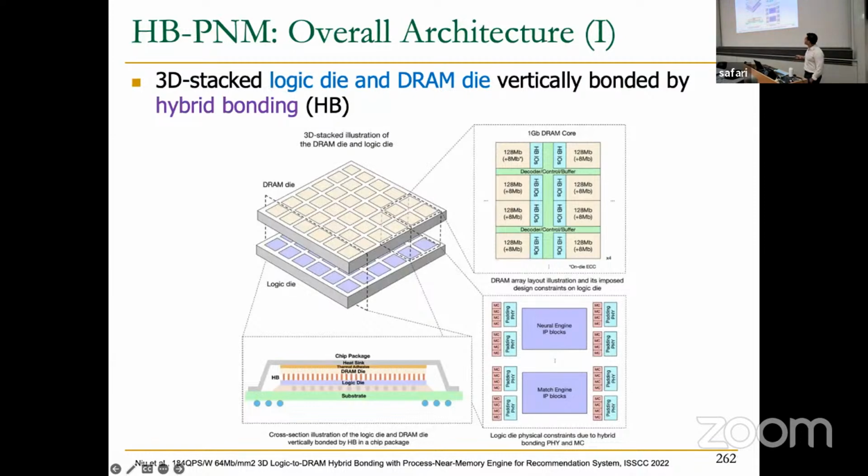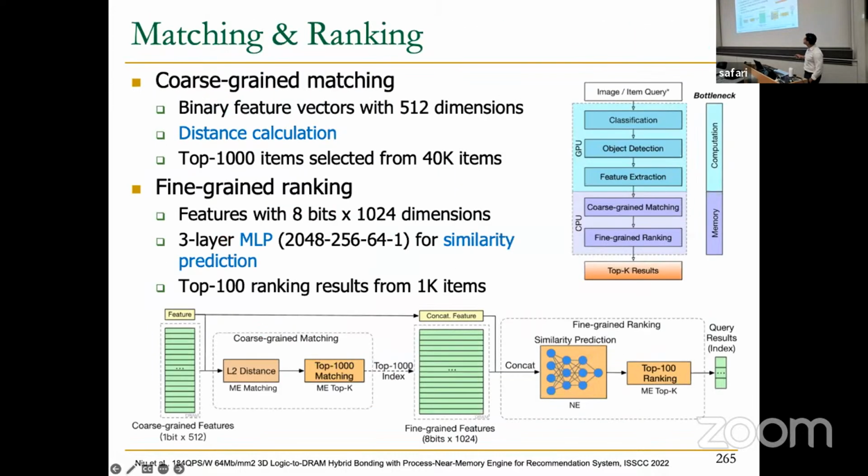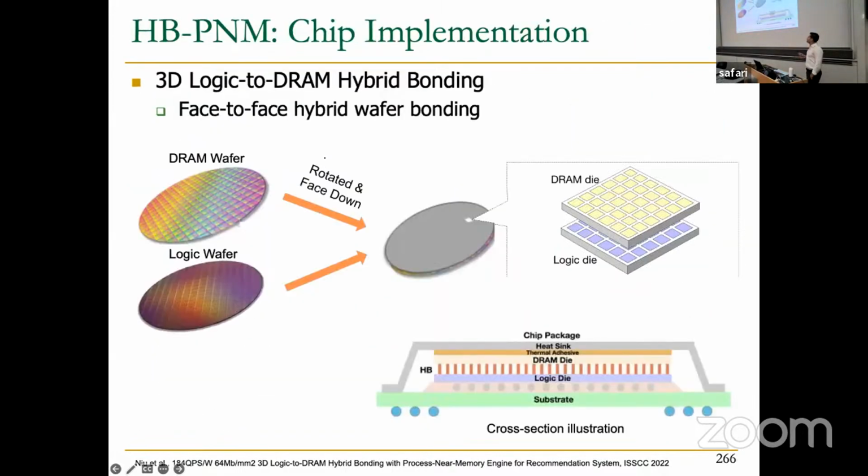So hybrid bonding is this process. Let me show here. You manufacture your DRAM wafer, and then you manufacture a logic wafer in their own manufacturing process, and then you flip them, and then they have what's called a wafer-to-wafer connection, where you use copper, I guess, to create connections from one wafer to another wafer in this hybrid bonding setup. So this is a quite newish technology. So it's quite impressive to see that a server manufacturer is already looking in this direction.